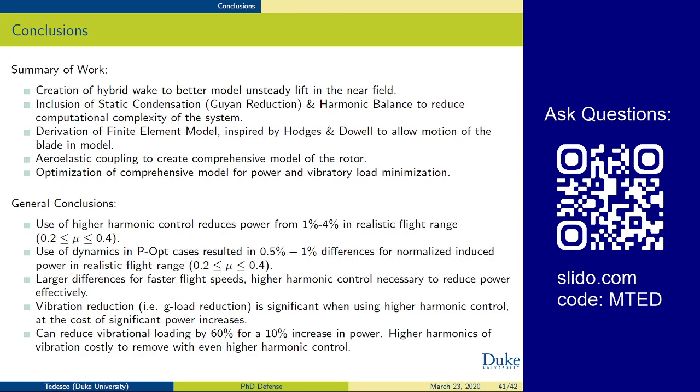Okay, so with all this being said, what have we done? Well, we've taken what we've already created. We've added a hybrid wake to better model the unsteady lift. We've included static condensation and harmonic balance to reduce the computational complexity. We've derived a finite element model inspired by Hodges and Dow to allow for motion of the blade. We've created an aeroelastic coupling with that structural model to create a comprehensive model of the system. And finally, taken all of it and optimized it for vibration and for power.